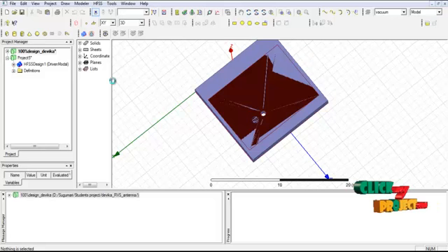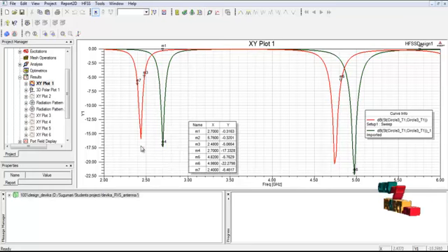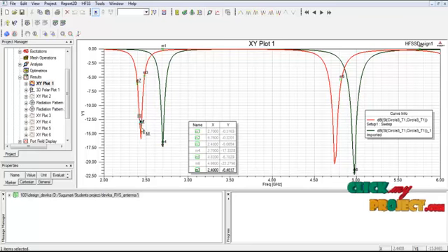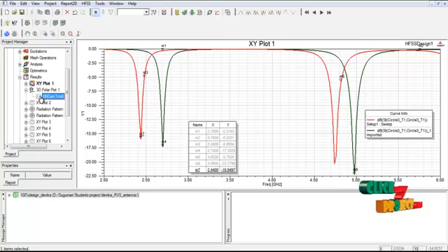So the results are, yeah, this is the return loss graph. Below minus 10 dB is the working condition of the antenna. For example, this point is indicated at 2.4 GHz with minus 15 dB, and M4 is at 2.7 with minus 17 dB. So like that, this is the return loss plot, and then the total gain.